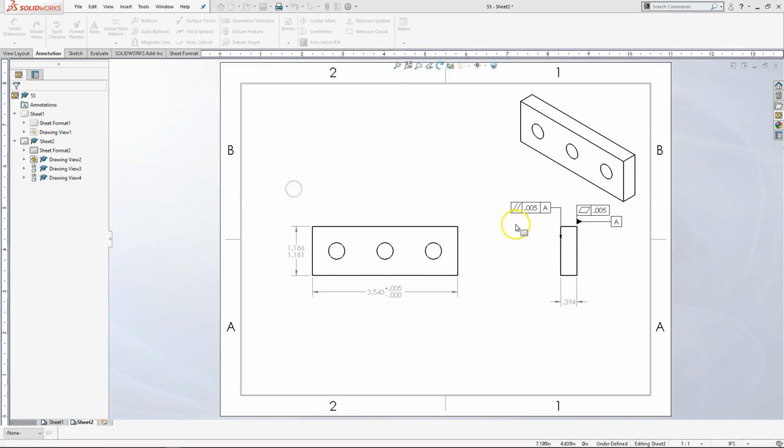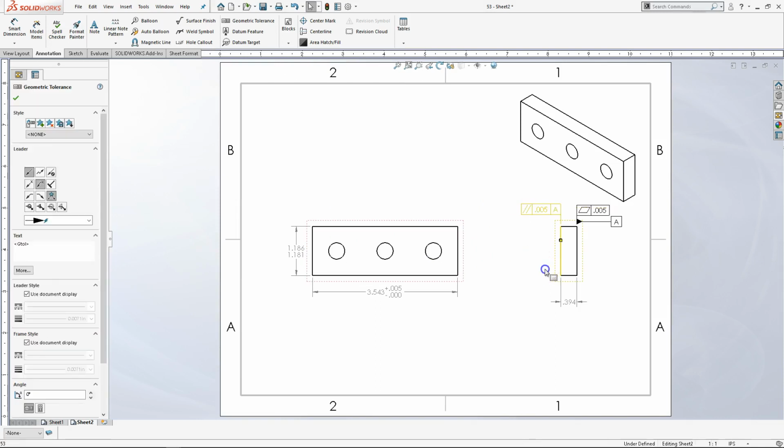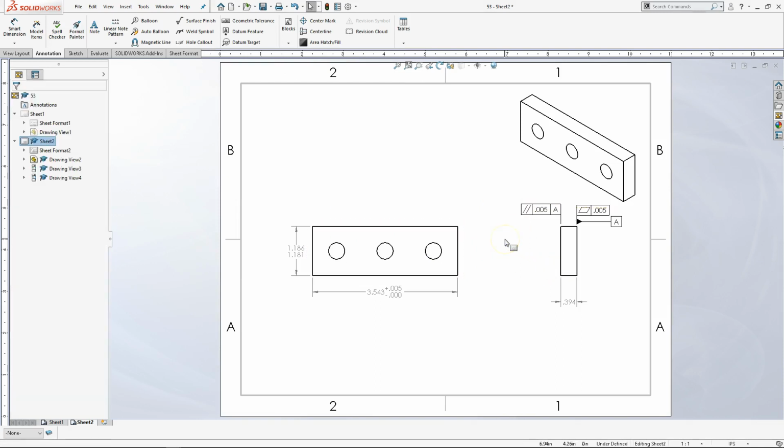All right, so the GD&T takes it up another level, but it ensures that you're going to have the fit as you send these out to the machine shops. These are critical. So one of the things that I like to reinforce is that as you're going through the assembly and you think, this is very important, this is critical, then you will want to start thinking about flatness, parallelism, positional tolerances, and going up through those next levels.